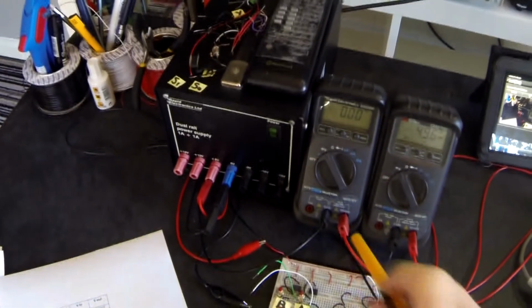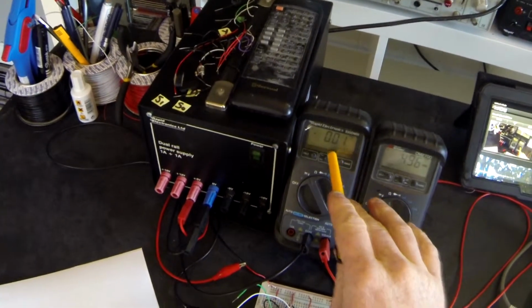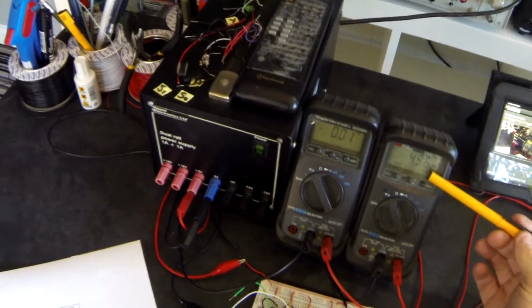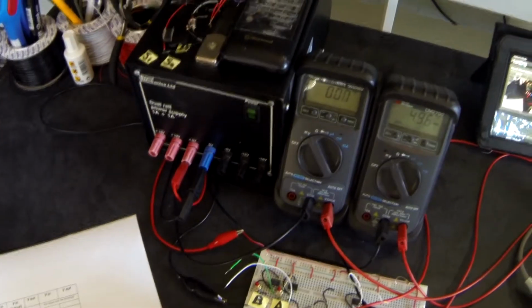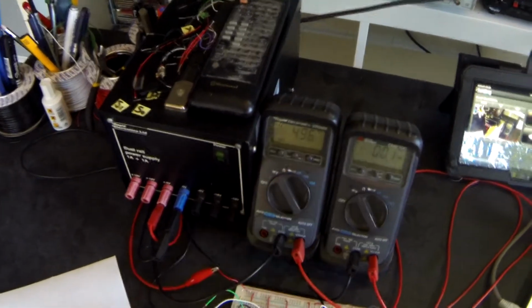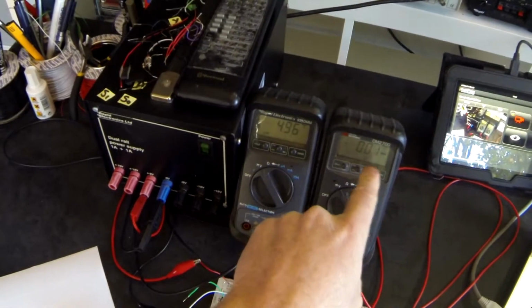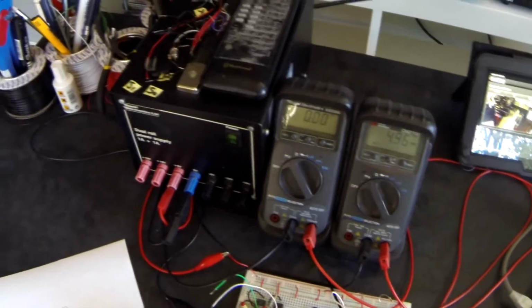So what I have here, I have my 2 voltmeters set up. This is V in and this is V out. At the moment V in is 0 and therefore we know that V out should be 5 volts, but it's clearly 4.96. So when I change V in, and I'm going to change it all the way, so now I have V in at 4.96 volts, my output has gone low. So a high in, a low out, a low in, a high out.